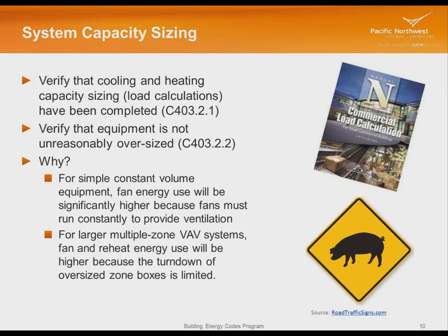So, looking at the sizing, the sizing requirements do allow for some reasonable safety factors, and obviously, if you come up with a size that's 3.2 tons, you'll need to jump up to the next size unit, maybe 4 tons. But you don't want to, like I say, double or triple the size of the equipment in a building.